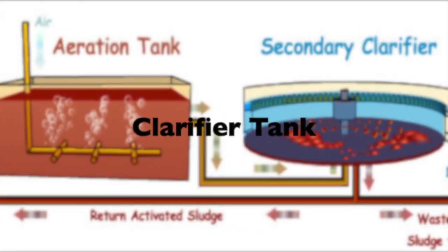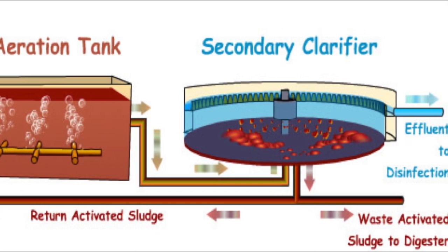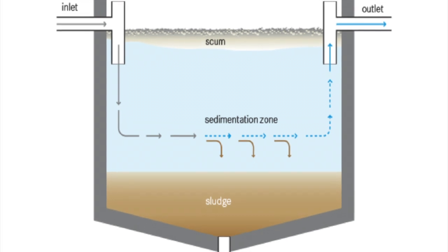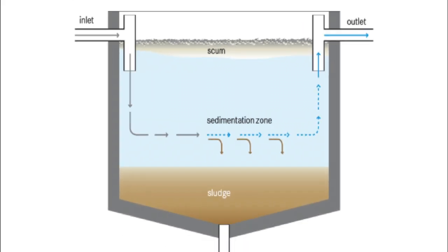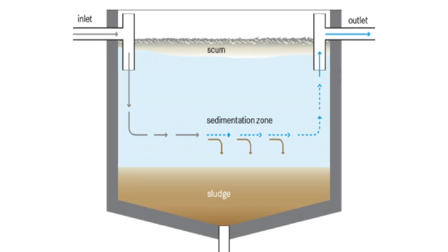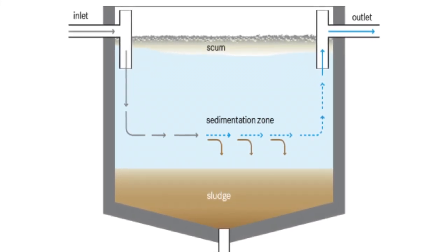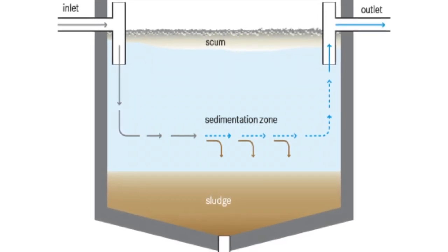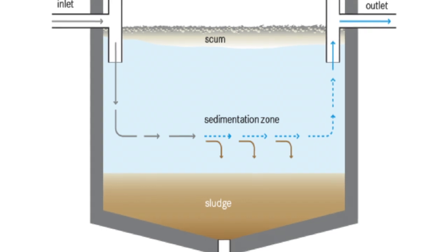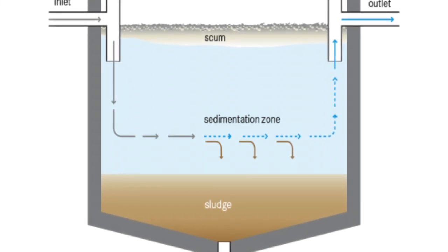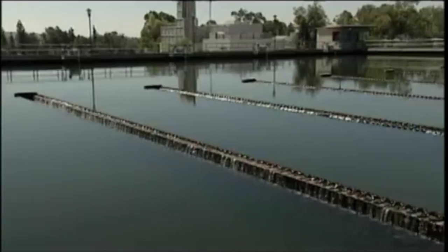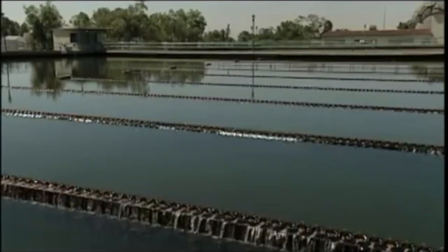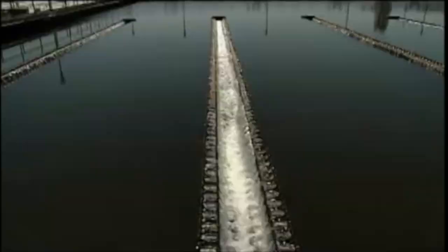Clarifiers or sedimentation basins are settling tanks built with mechanical means for continuous removal of solids being deposited by sedimentation. The control variable is the water turbulence in the tank. The manipulated variable is the water inlet and outlet velocity. Baffles are used to prevent fluid velocities at the tank entrance from extending into the tank. The solid particles are kept in suspension in water as long as it flows with sufficient velocities and turbulence.